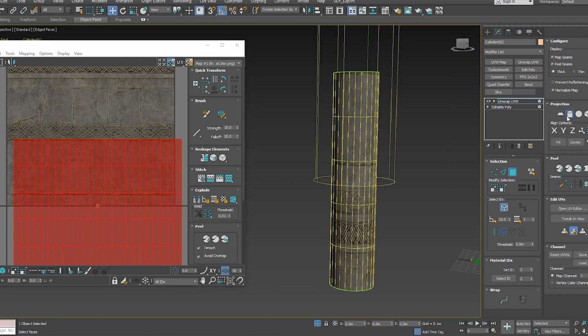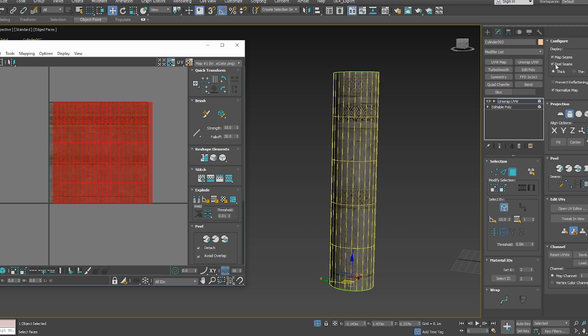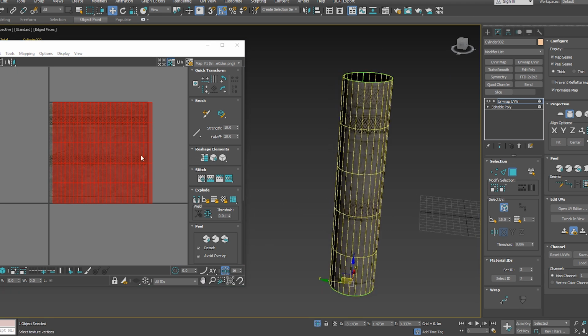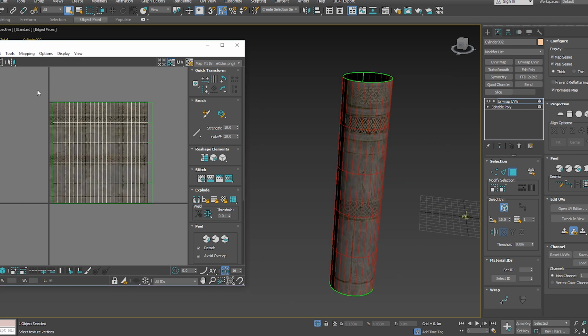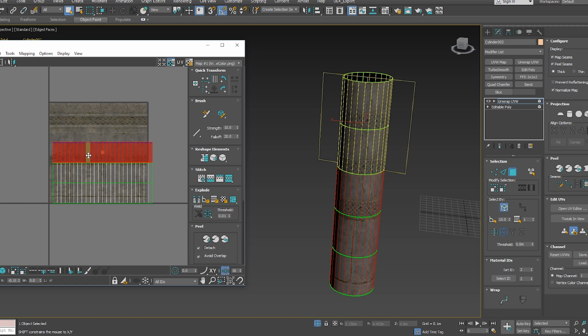So yeah, I just used a quick cylindrical projection just to get a seam down one of the edges, and then all of it wrapped around the entire texture. And then I just simply break those UVs, move them down, break those, break those, break those, and then just stack them all on top of each other.